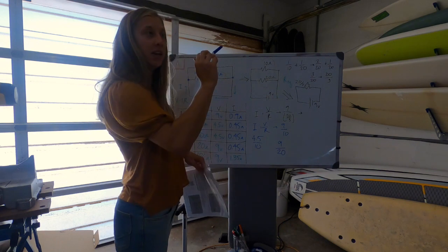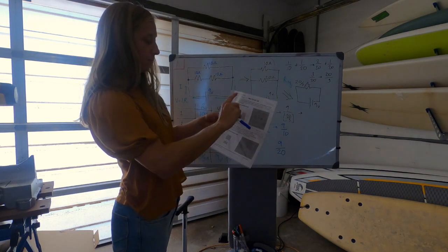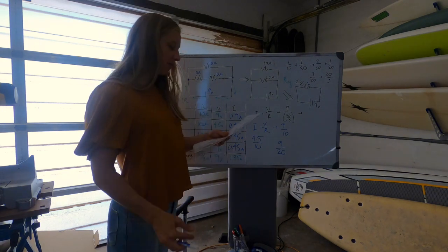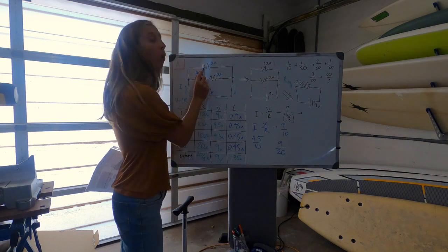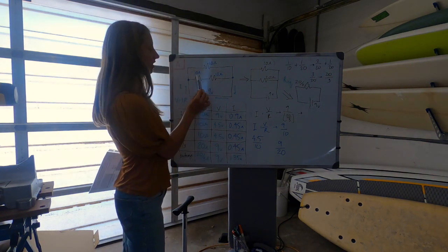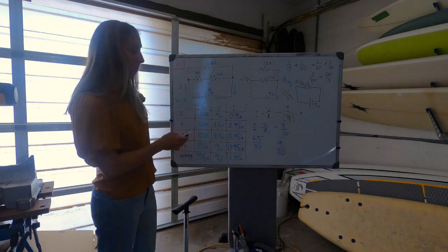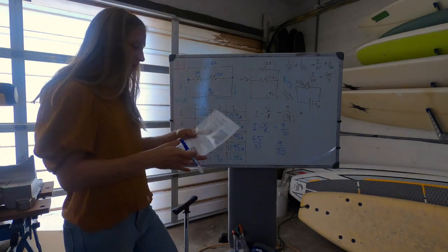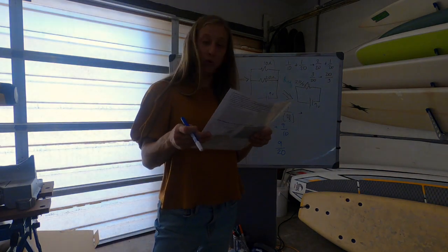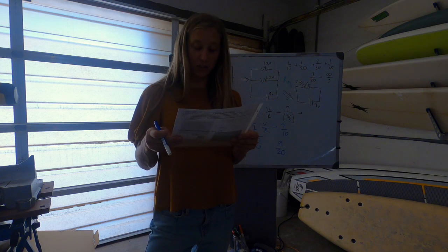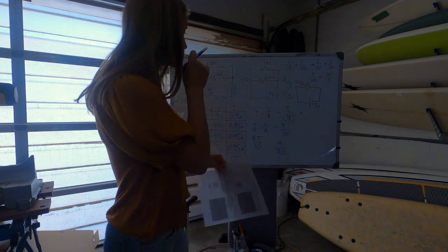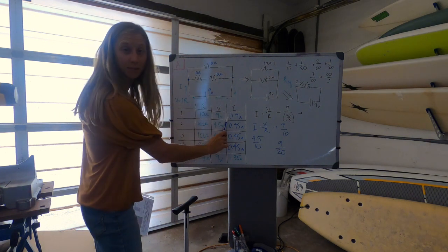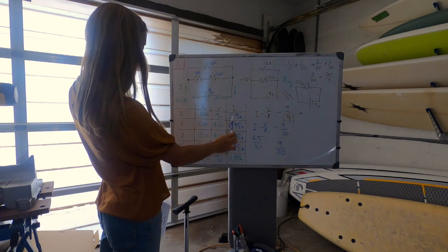So on my paper, for question 2, I would basically just write resistors 2 and 3 are in series. And then for parallel, what's in parallel? Well, resistor 1 is in parallel with resistors 2 and 3 together. So I would say in parallel would be resistor 1 and resistors 2 and 3 together. Okay, let's see. Number 3, compare the current in the top branch to the current in the middle branch. Okay, so what's the current up here?